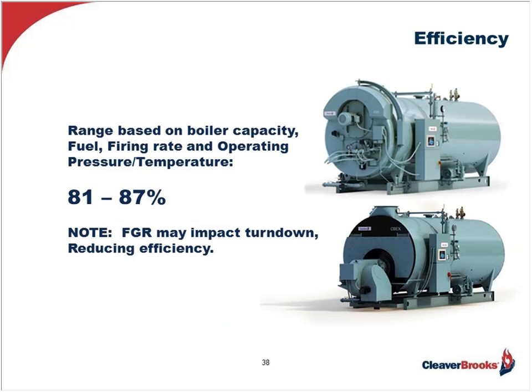And lastly, before moving on to the engineering portion of this program, I wanted to say something about the expected efficiencies for the properly designed Firetube boiler package. As you can see on the screen, and depending on boiler capacity, the fuel, the firing rate, and the operating pressure and temperature, these boilers are very efficient, averaging anywhere between 81 and 87% efficiency. However, there's a word of caution here. If FGR is required to reduce the NOx to, let's say, 15 parts per million or less, this will probably impact the turn down of the burner, which may increase the cycling. And that can cause some significant efficiency loss depending on the frequency of that cycling. So keep that in mind.